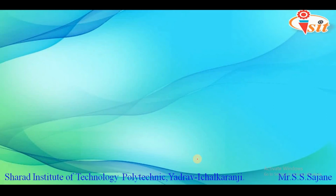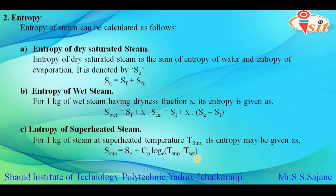Now we will start with the next property of steam, that is entropy, and just like enthalpy we will see how to calculate the entropy for various conditions of steam. So let's start with the first point, that is entropy of dry saturated steam. It is defined as the sum of entropy of water and entropy of evaporation. And this entropy of dry saturated steam is denoted by Sg, which is shown in the slide.